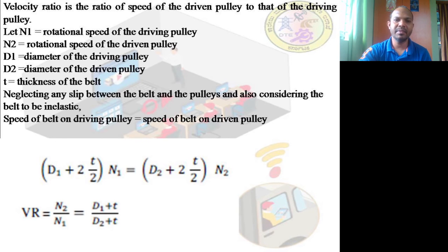So that is the reason why we always discuss this velocity ratio with respect to the thickness as well as the diameter of the pulleys. Because the flat belts tend to climb towards the higher side of the pulleys, pulleys were meant to be slightly crowned, so that there might be a little drop in the velocity on certain occasions.